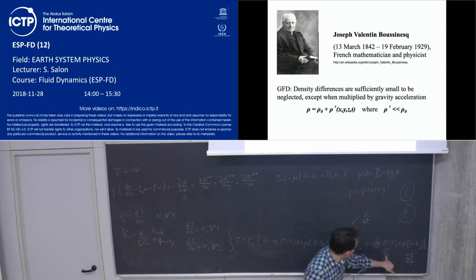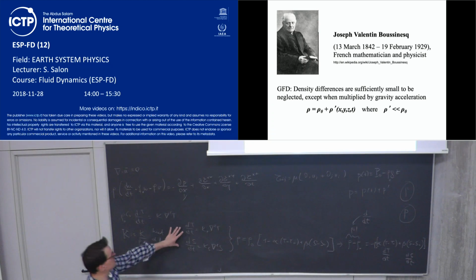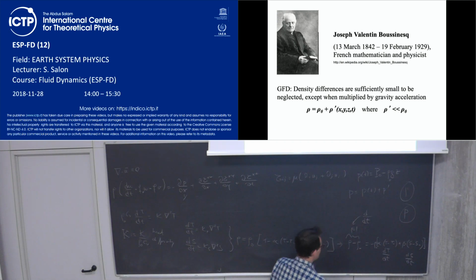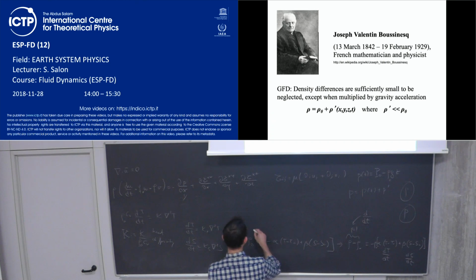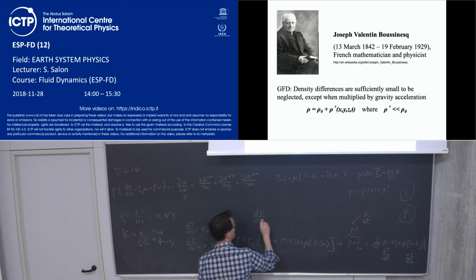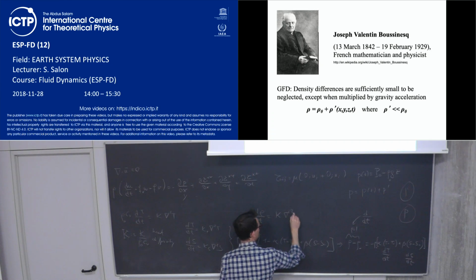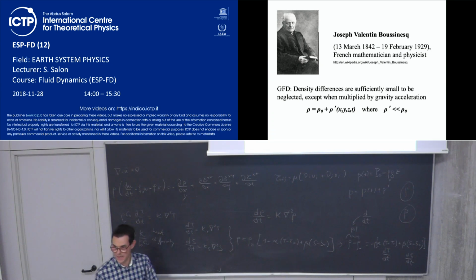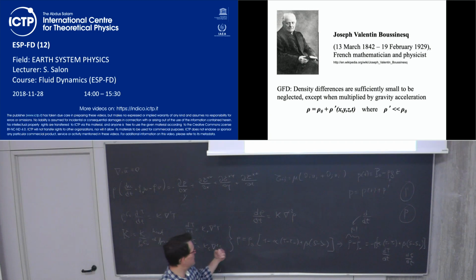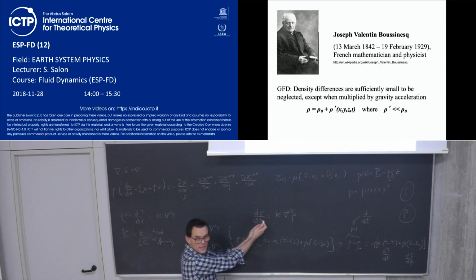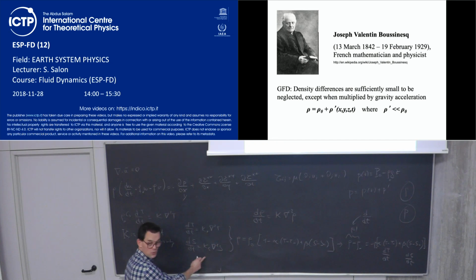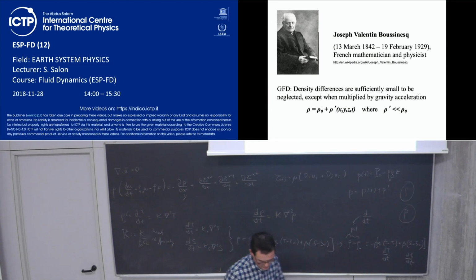Okay. So the dT over dt, the dS over dt, we can use the two diffusion equations, and what we obtain is that we can find a new equation, which is this one. Okay? So thanks to the Boussinesq approximation, we were able to put together the equation of the energy and the equation of state in one single equation. Okay? Don't forget that we still have to keep this one, but at least we have saved one equation.